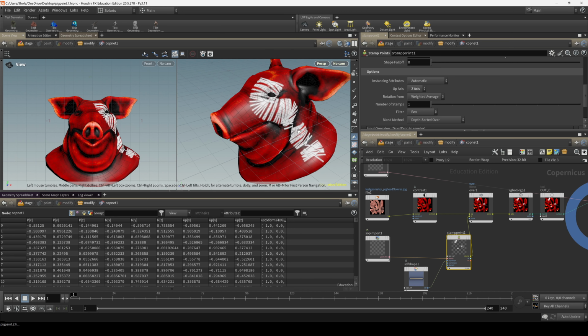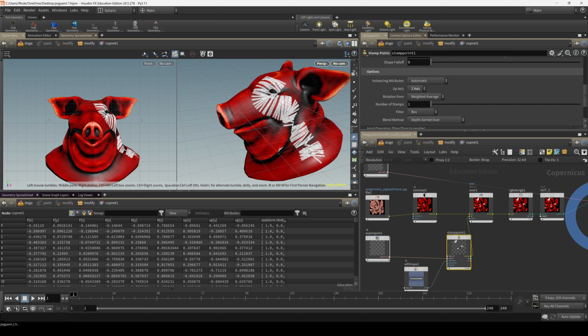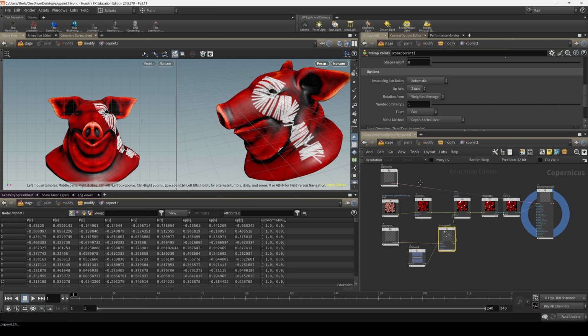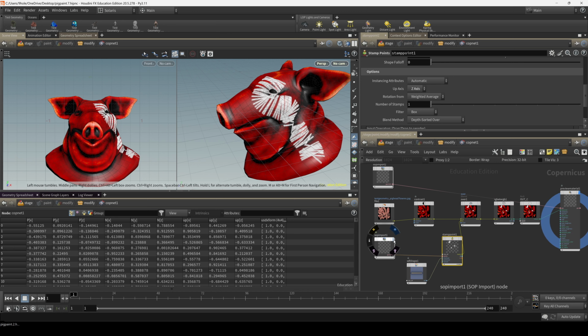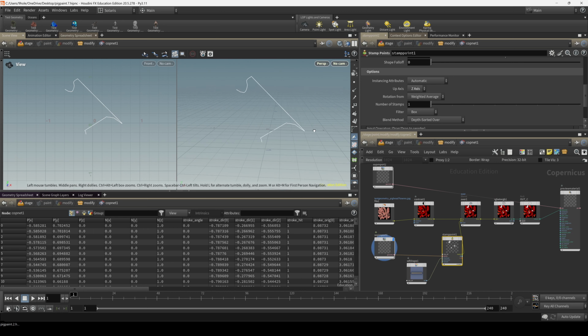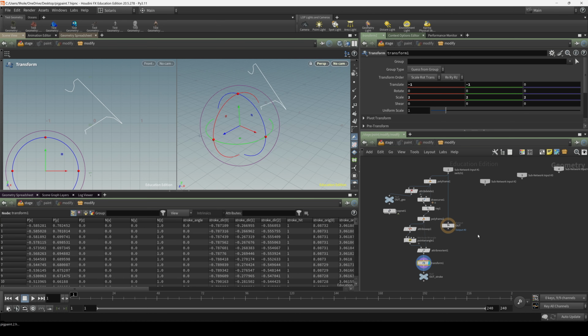that I now have orientation for my curve. And so the problem with this is that where it crosses the UV seams, it breaks up. And the reason being, again, is that if we look at our drawn curve, once it's put into UV space, it jumps across the seams.